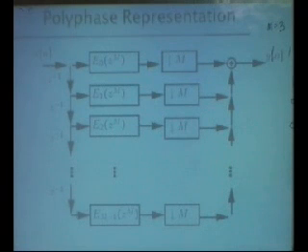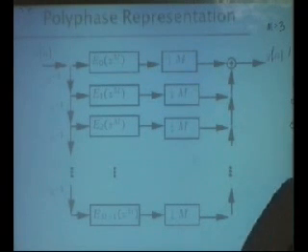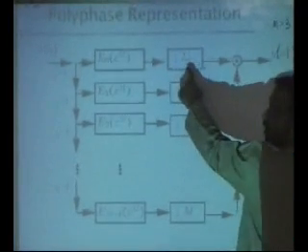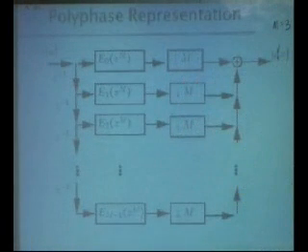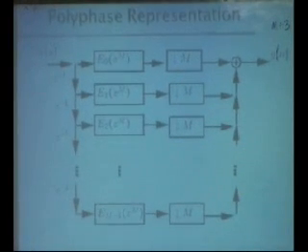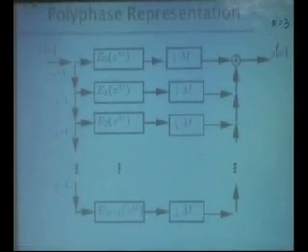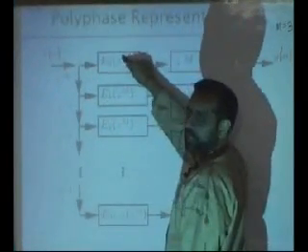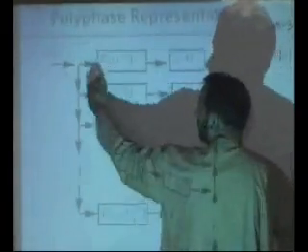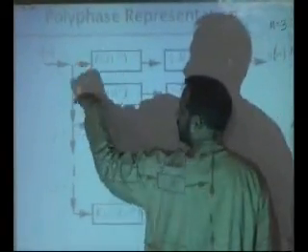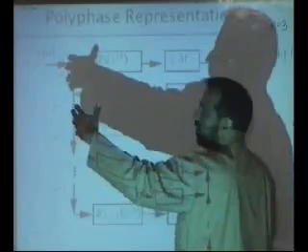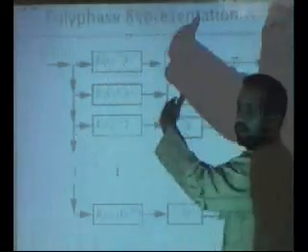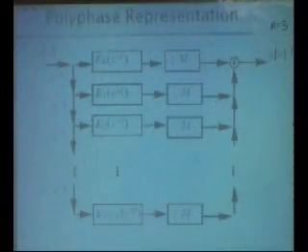Now is the trick which is played, which says really the throwing away of samples here is equivalent to throwing away of zeros here. If you are throwing away every so many samples, if you bring this on this side, it will eat up this M. Once you are inputting to this system, then you throw away samples and then pass it through a filter where there are no zeros, and you can easily check this.